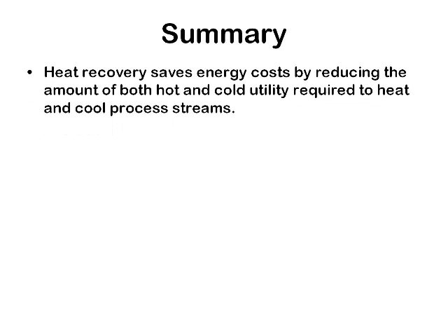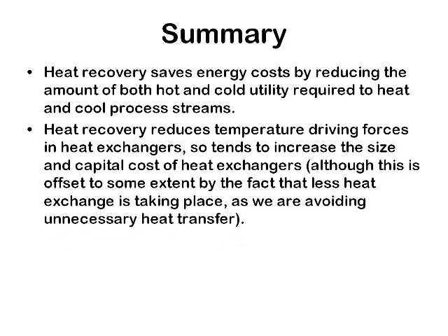So, in summary, heat recovery saves energy costs by reducing the amount of both hot and cold utility required to heat and cool process streams. Heat recovery reduces temperature driving forces in heat exchangers, so it tends to increase the size and the capital cost of heat exchangers, but this is offset to some extent by the fact that less heat exchange is taking place because we're avoiding unnecessary heat transfer.